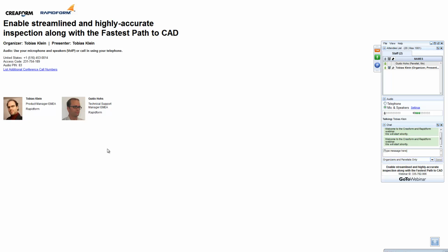So another question, can we use this software to obtain surface roughness of the object scanned? Actually, if your scanner is capable of capturing the surface roughness in the desired accuracy, then we could use, for example, the color deviation mapping and the tolerance to see where your roughness is out of tolerance or in tolerance. This is possible, yes. However, your scanner or point acquiring device has to have an accuracy which is inside your roughness.